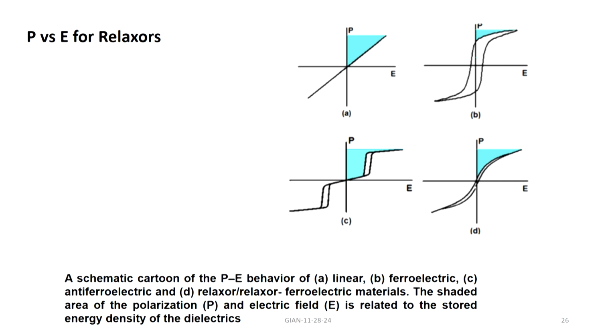This is just a piezoelectric, and that is P versus E is linear. So, when you go to a ferroelectric, that is shown in B, where this is the characteristic that you see for PZT or barium titanate, and where there is saturation of the polarization, then you go back to 0 electric field, there is remnant polarization.